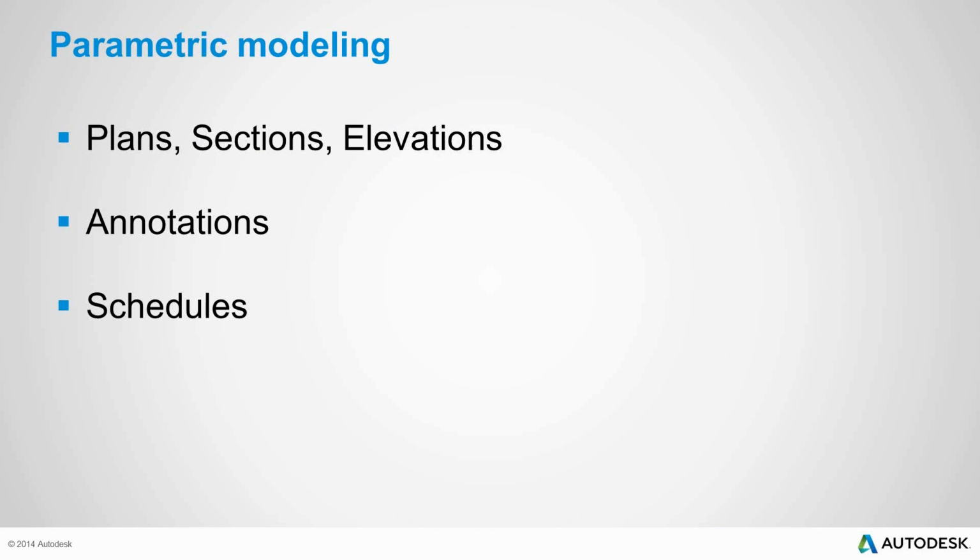Parametric modeling is when all your geometry in the model is moving: you're pushing and pulling, adjusting your areas, and moving your walls, roof heights and floor to floors around. All of this is adjusting simultaneously. There's no refreshing. You don't have to update stuff. It's one model that moves simultaneously. So I want to go over parametric modeling, how to quickly annotate that model with your tags and keynoting, and then the power of using schedules for scheduling out room areas and things like material schedules as well.